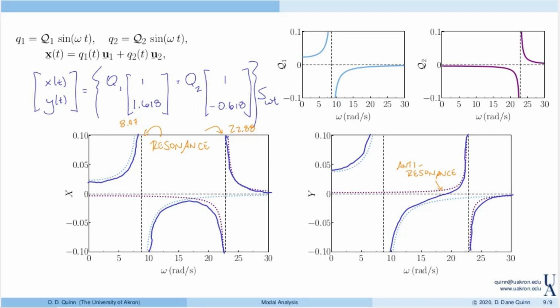And it actually has practical application for vibration isolation. But these are two of the interesting features that can occur in the response of the system as we vary the forcing frequency. Here we have each modal solution blowing up, and with this anti-resonance, effectively the two modes interfere at the second block and produce zero response.